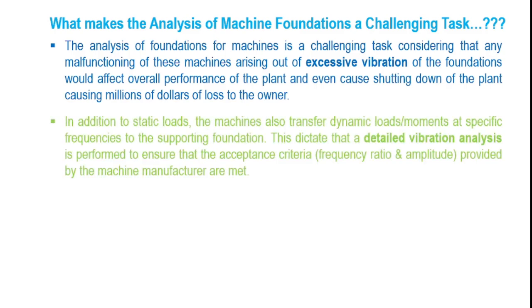Next one: in addition to static loads, the machines also transfer dynamic loads or moments at specific frequencies to the supporting foundation. This dictates that a detailed vibration analysis is performed to ensure that the acceptance criteria, frequency ratio, and amplitude provided by the machine manufacturer are met. So this is another important fact to be addressed.